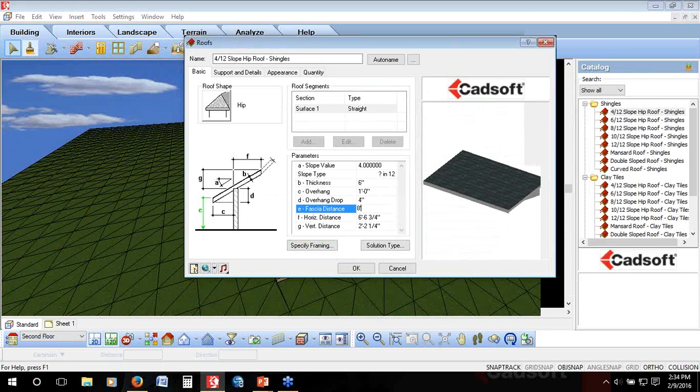When I click in any of the other dialog boxes that affects that, like our horizontal distance might change, this overhang drop here, the only time that is going to change, and you'll see a distance difference there, is when I change slope and overhang, because that's really what's going to change that D value that you have in there.